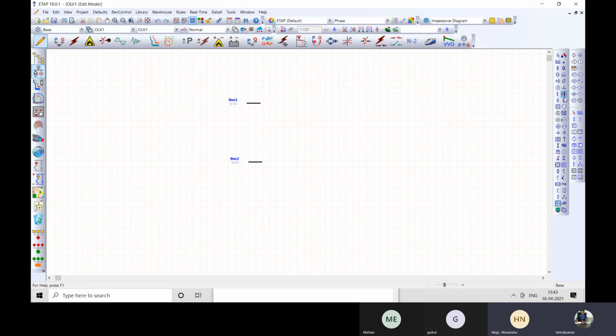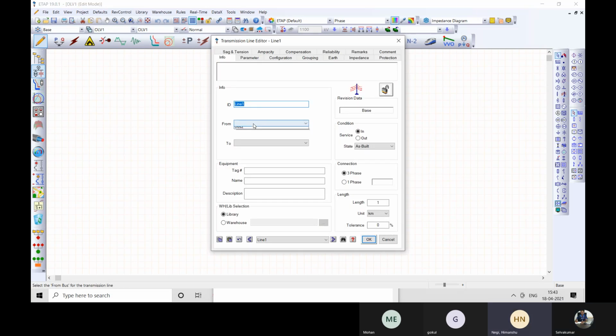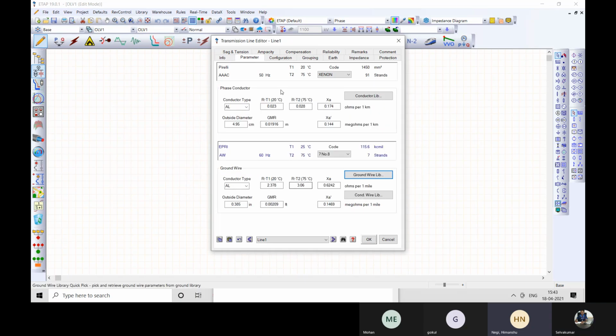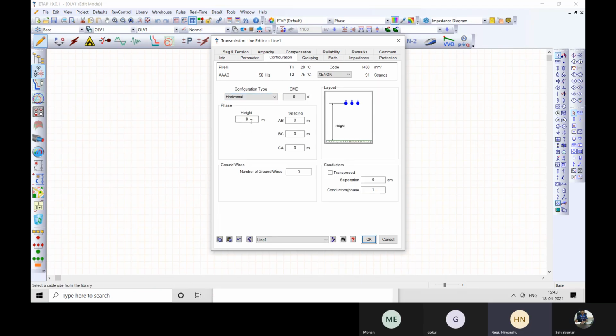Okay. So if the substation itself is say 10 ohm, and there is a transmission line on the other side, 30 kilometers as well, and there are so many tower footings connected, 10 ohm, 10 ohm, 10 ohm as a standard value. If we parallel the substation plus all those towers on either side, that impedance will no longer be 10 ohm, it will be like 0.01 ohm and an angle of something like 30 to 36. So that's what is called the concept of chain impedance. Right.